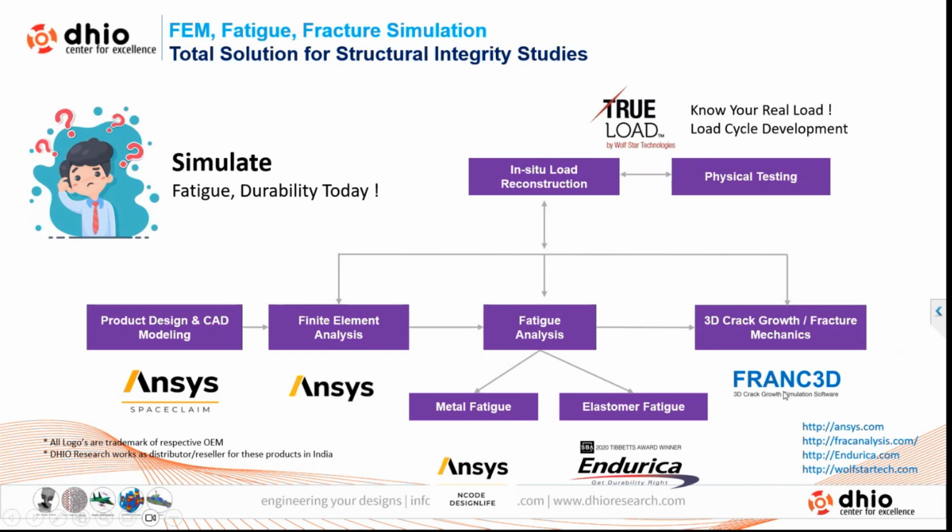Franc3D is a 3D crack growth simulation that works on the M-integral based approach as well as the displacement correlation method or the J-integral based approach. We also have a probabilistic approach, because Franc3D is a more deterministic approach where you get the crack introduced and the crack propagation, where the anomalies coming from manufacturing and other aspects are not specifically handled. For that we go with DARWIN.